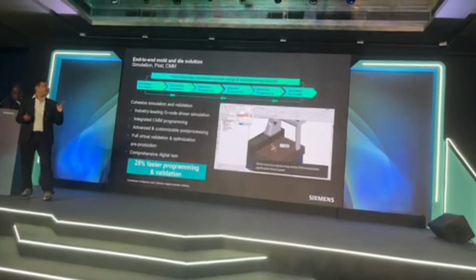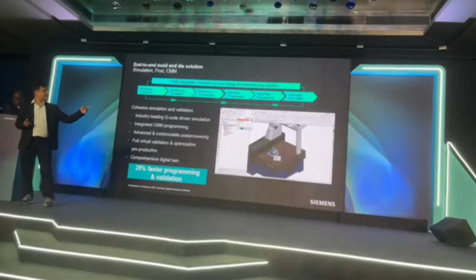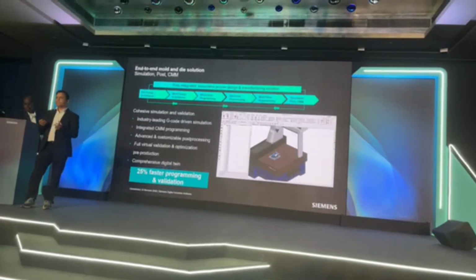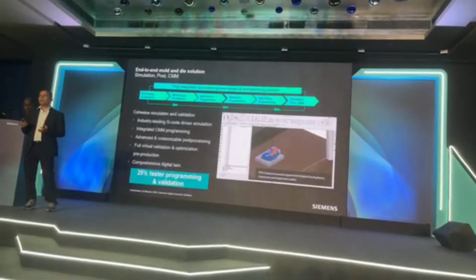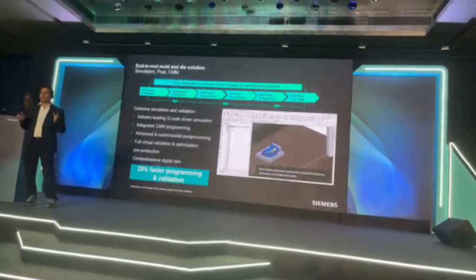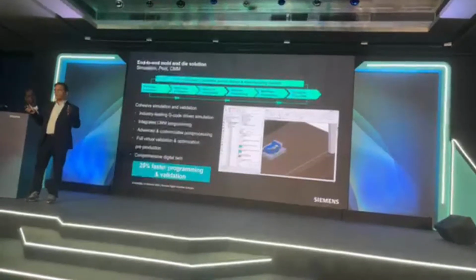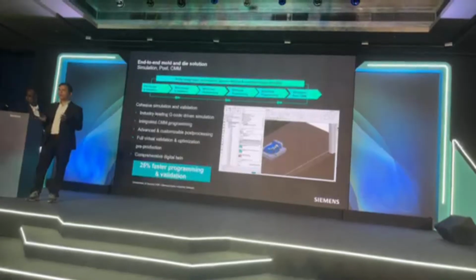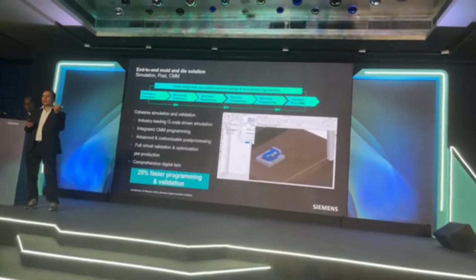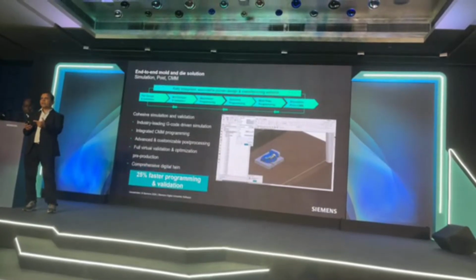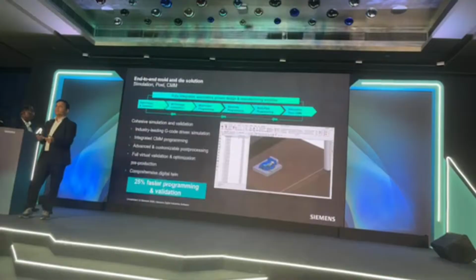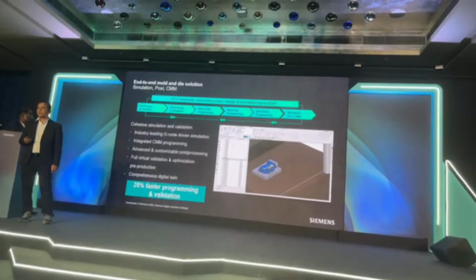Once the part is machined, what you do, we have CMM inspection. You can use the CMM to check whatever was machined, because at the end, once the machining is done, unless you inspect it, you won't know whether there is material left over or excess material. The inspection is also integrated. So what Dax suggested, the whole CAD and CAM integrated, that overall process is streamlined so that you get the design, the mold insert programming, electrode programming, and then the plate machining, and then inspection. It's all interconnected. If there are any changes in the design, automatically all this will be impacted in the process.